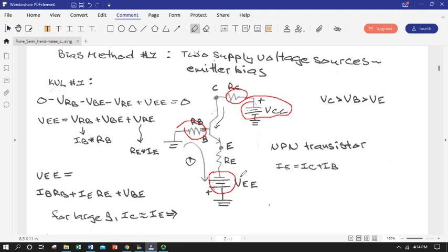What we want to do is understand how these values, our biasing supply voltages and biasing resistors, affect the relationship between a base current, a collector current, which is generally the thing that's going to get amplified, and the collector emitter voltage drop? Because those will be the things that will determine what our circuit output is in terms of an amplified signal later on, which we'll get to in the next chapter.